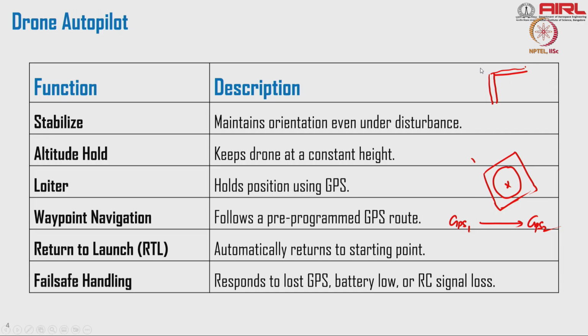What kind of fail-safe can we provide? Suddenly I am seeing that it started maneuvering very aggressively, closer to a target. I should be able to abort the whole mission. I should be able to kill the drone, and what I mean by kill is I just have to stop the functioning of the drone. I need to stop the motor so that there is no thrust.